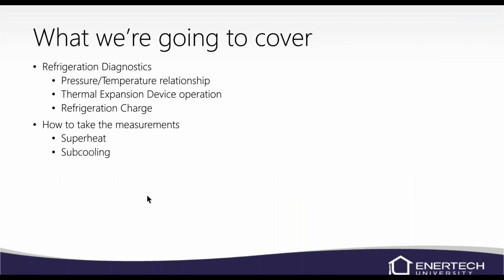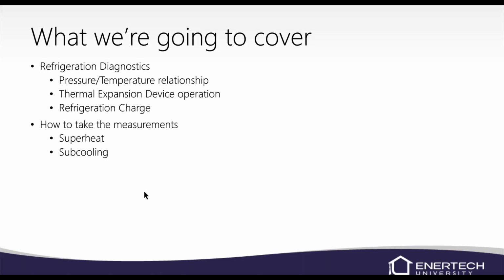So we're going to cover basically the pressure temperature relationship, the thermal expansion device, or the TXV, the refrigerant charge, and then how to take the measurements, the superheat and subcooling, and then once you get those readings, what those mean.